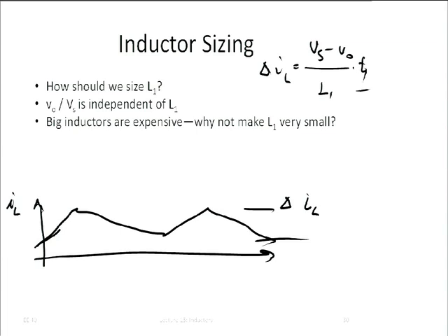We don't want to get into that. Obviously, faster makes it that these ripples are at really high frequency, and so that's nice. On the other hand, making the circuit go at a very high speed actually dissipates more power because we need to turn on and off the switch, and that costs a little bit. So, yes. Well, this is a side question, but how does one make such a square wave that goes on and off really quickly?